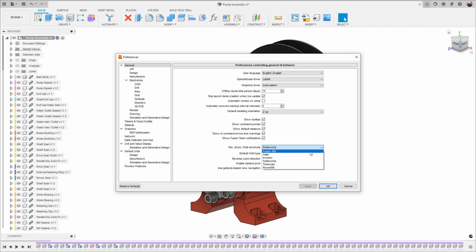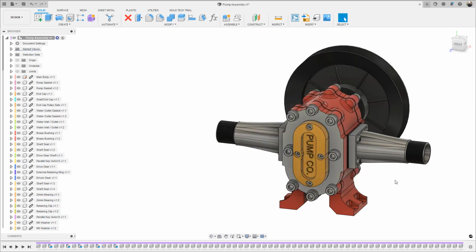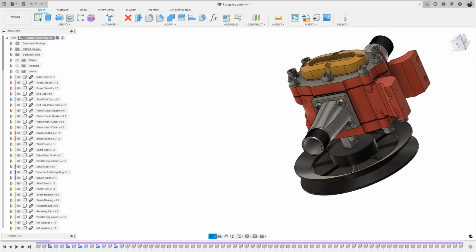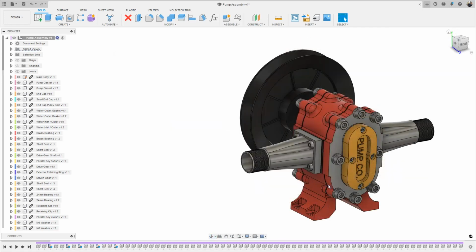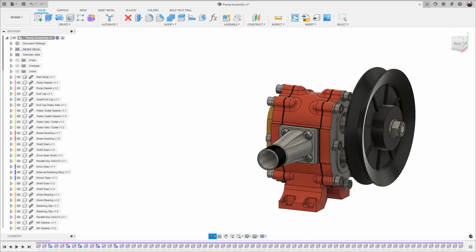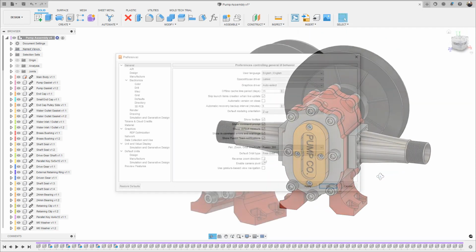The next choices we have are a bit more specific. First, we have our orbit type, free or constrained. These will behave slightly differently and are again up to personal preference and may roll over from previous software usage. For instance, our PowerMill software uses a constrained orbit, so that will be pre-selected with that preset. The constrained orbit is slightly more simple, constraining the axis in which you orbit, but the best way is to try it out and see what you prefer.